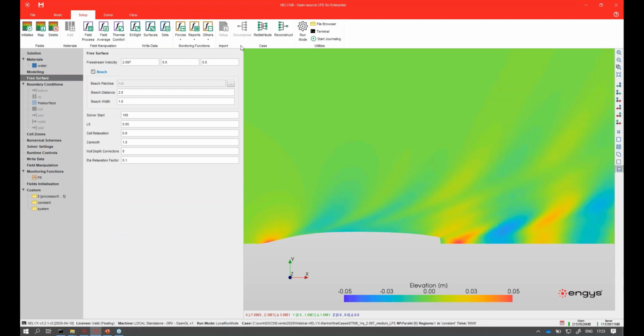This is where you prescribe the settings for the linearized free surface boundary conditions. So you have to define the free stream velocity here, and the numerical bits where you basically apply some damping to the domain. This is a sort of a ring which is placed inside the domain with a specific distance and width, and a series of patches and surfaces where it's computed from, and then a series of parameters such as relaxation factors.